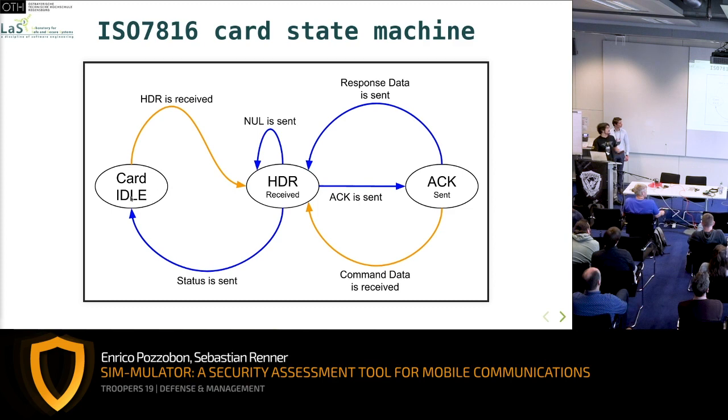If an error happens during the header, for example the command is not valid, then the card goes directly from idle to this state, and then it immediately returns an error status.